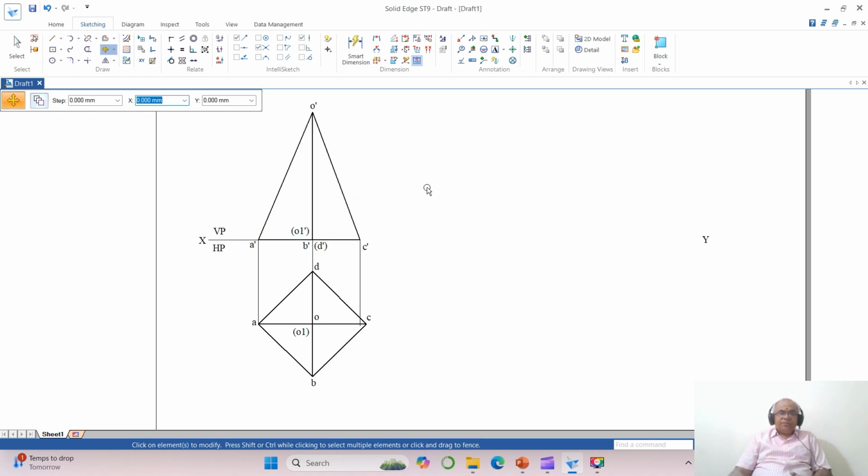Now we want to copy this to the second position, the first position front view. So enable copy, you just select this, go to this, and by holding tab, take the Y position as 0, and you make sure copy is enabled. You just click on this and click on the first button of the mouse.